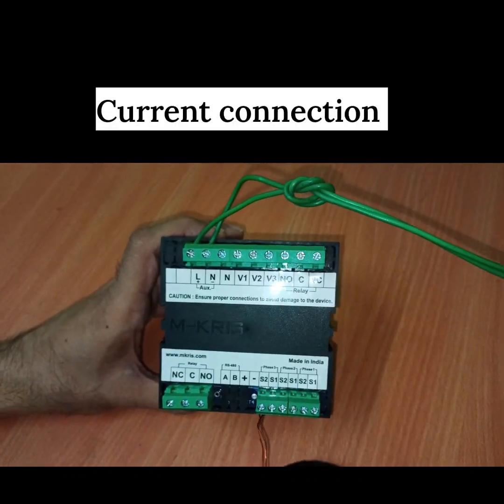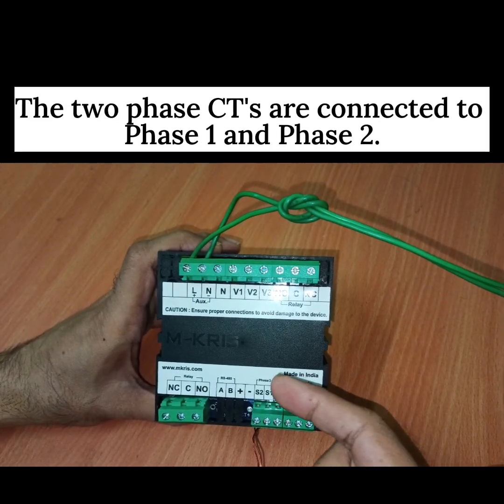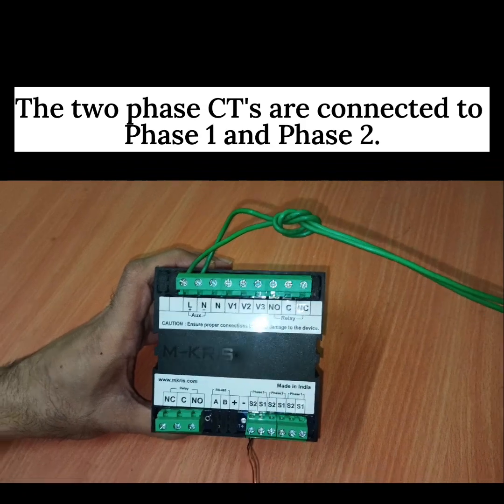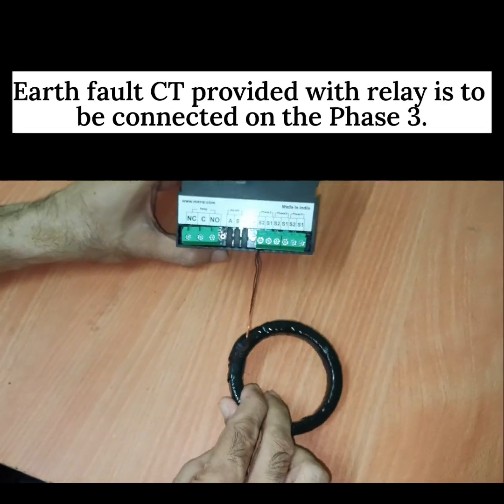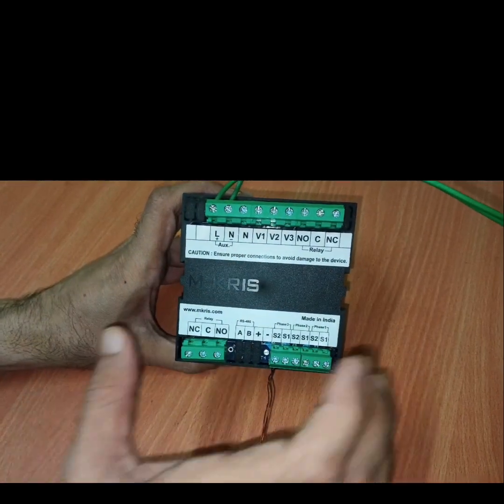As far as current connections are concerned, the two phase CTs are connected on phase 1 and phase 2. Earth fault CT, which is provided with the relay, is connected on the phase 3. This is about the connections.